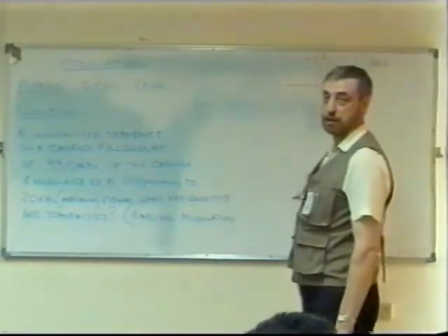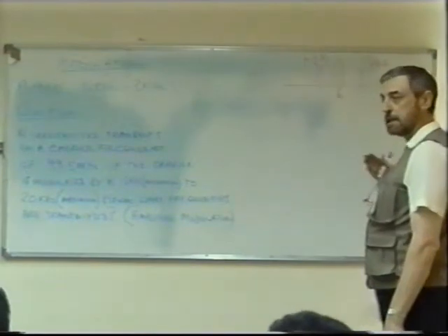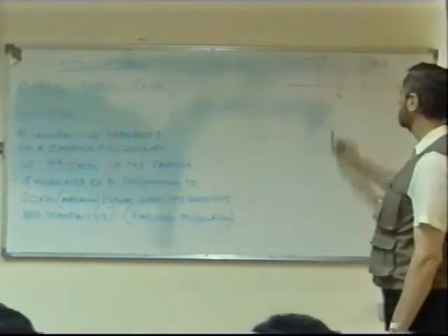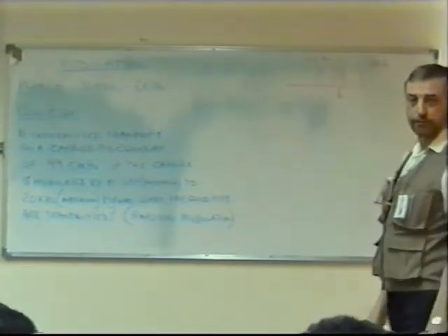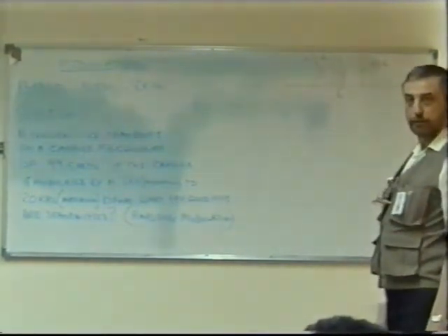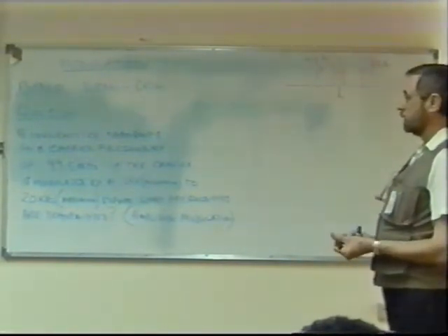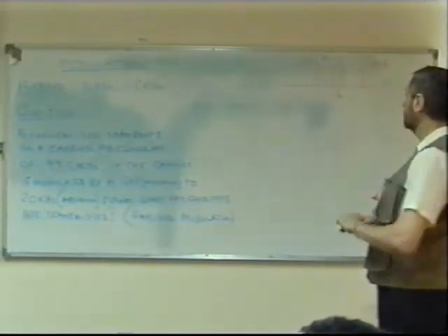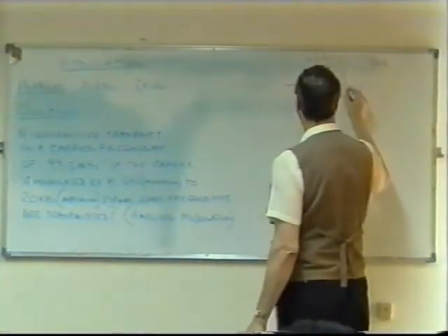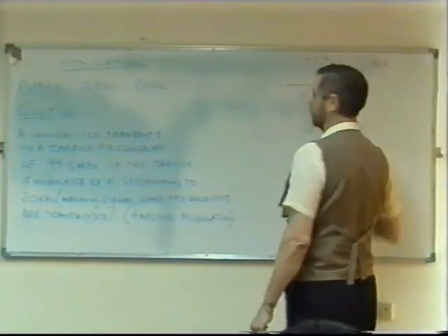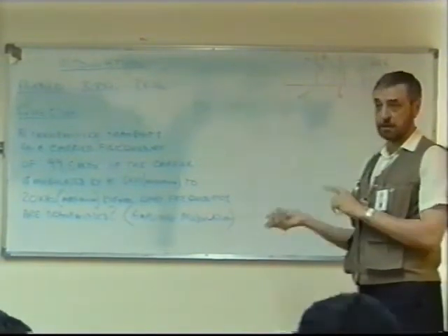The question wants to know more or less what frequencies are actually transmitted. And if you think about the little rule I've given you, you should be able to put values to all these parts of our graph. The carrier plus 5, minus 5. And the carrier plus 20, minus 20. There are four different frequencies we can calculate here: FC minus minimum, FC plus minimum, and so on. It's the difference and the sum.